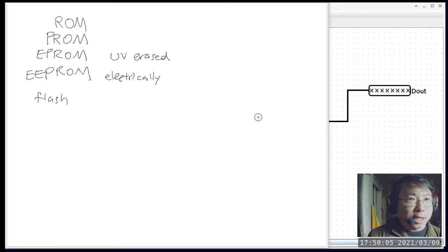But when it comes to flash memory, from the programming perspective, it is also entirely different. When you look at instructions inside the computer, the instruction to update a location in RAM is super easy. But if you want to change the content of a location in flash memory, you actually have to run a subroutine to do it. It is actually fairly complex. So there you have it.